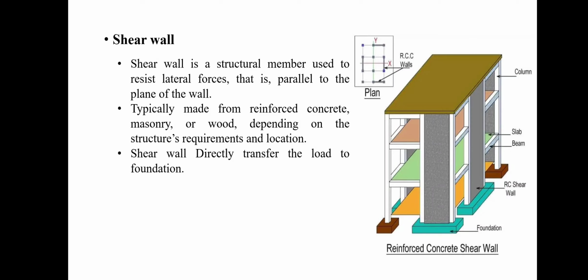The shear wall starts from the foundation and ends at the top floor, acting as a vertical cantilever which helps the weaker portions of the building, like where the beam and column join, during seismic activity. The joint of beam and column is more sensitive at the time of seismic activity and has a chance to collapse and get deflected. By using a shear wall, we reduce the effect on those weaker points by providing them extra support.